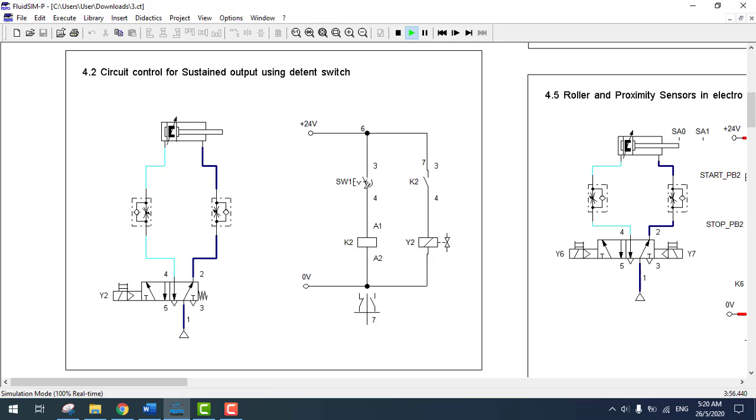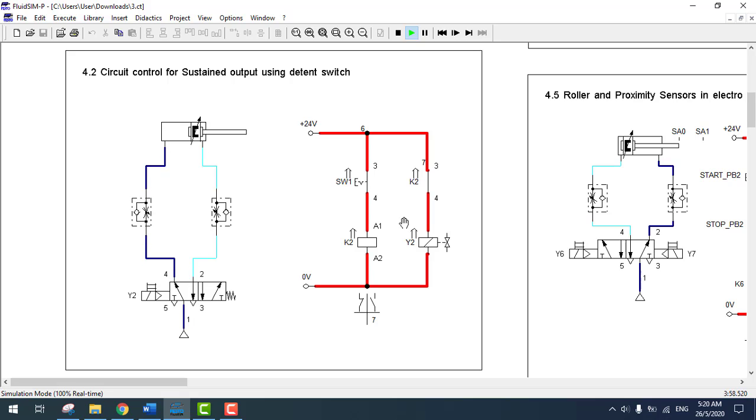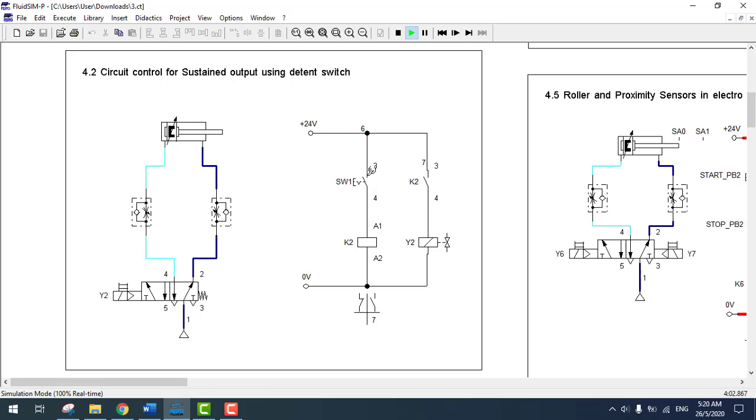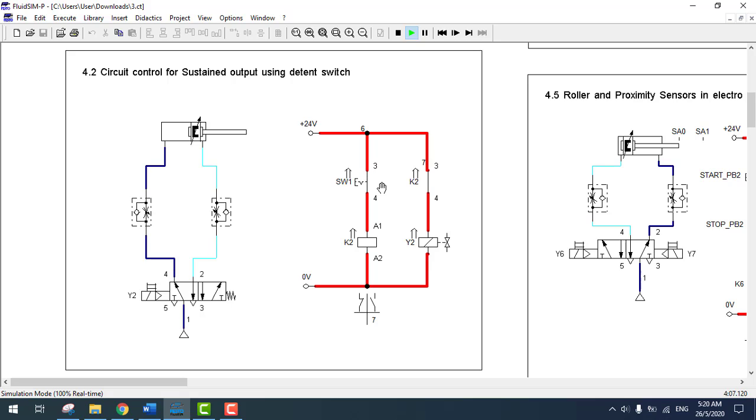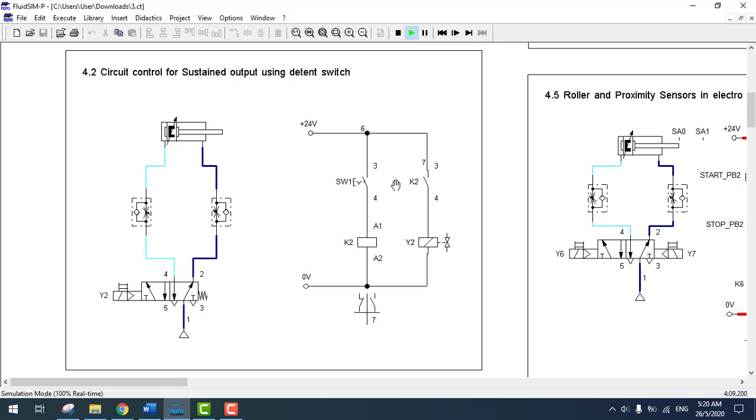The valve solenoid generates the electromagnetic field to shift the spool valve inside the 5-way solenoid valve to the left side. Compressed air supply will fill up the double acting cylinder through the one-way flow control valve. The one-way flow control valve regulates the flow rate of compressed air to fill up the volume area of the cylinder.